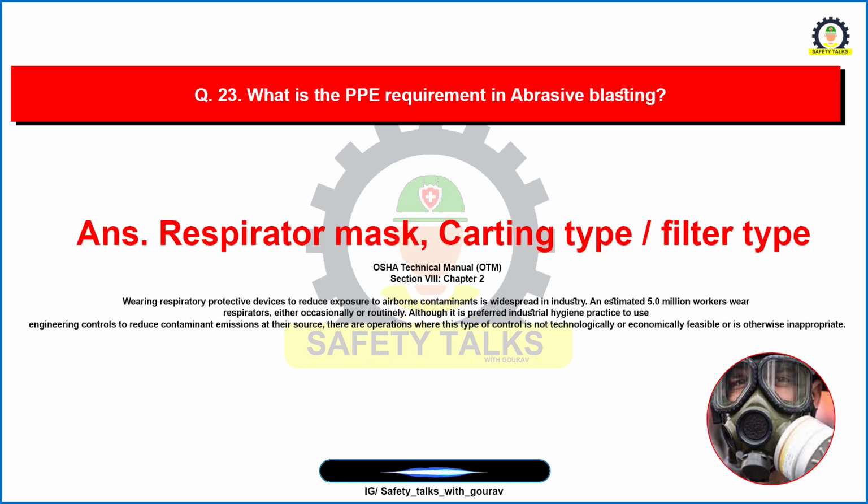It goes like this: what is the PPE requirement in abrasive blasting? Like, what is the mandatory PPE requirement in abrasive blasting? So the answer will be respirator mask, cartridge type, filter type.